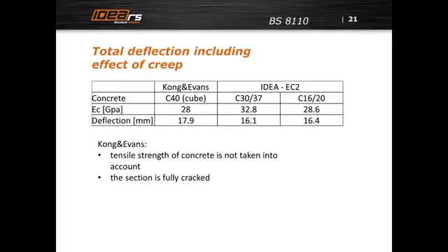This I do not consider a positive feature, and I would like to warn you, because in case the producer of concrete really wants to make a nice compressive strength, then they use admixtures which will make the modulus of elasticity lower. So I would say this is not a very realistic value.